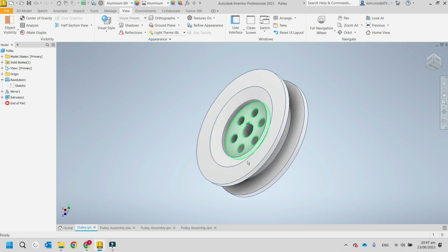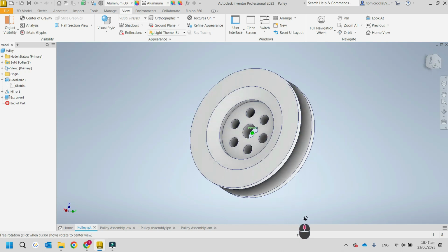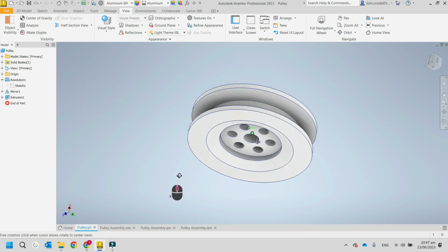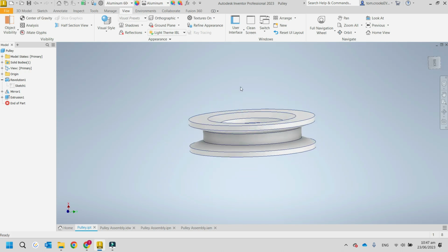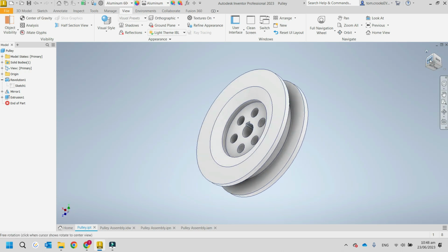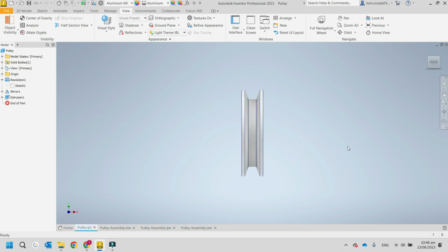So now when I rotate around it, the shortcut for that is to hold shift and your middle scroll button, that you will be using a lot, so remember that. It's also in the description on Moodle. So shift plus control. I get lost. Okay, so I'm drawing something, I'm lost, I can't figure out how to get back to where I was. I can come to this home or the view cube here and click around it and find my way around it a bit easier.